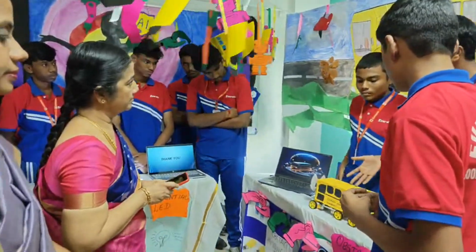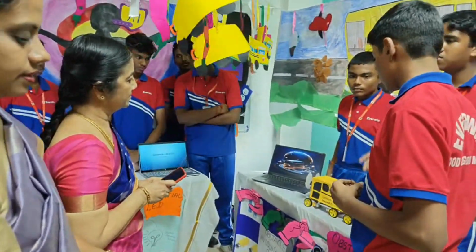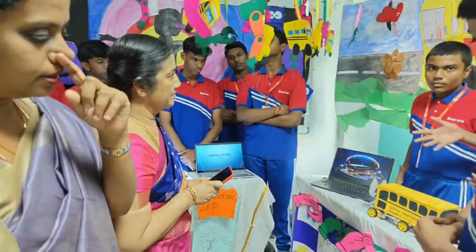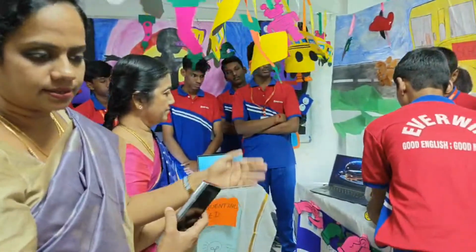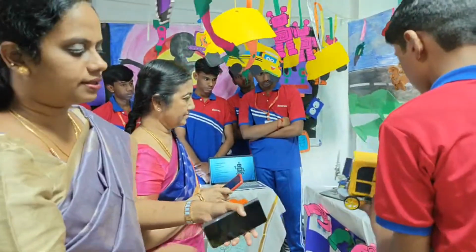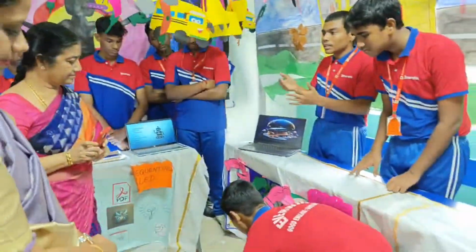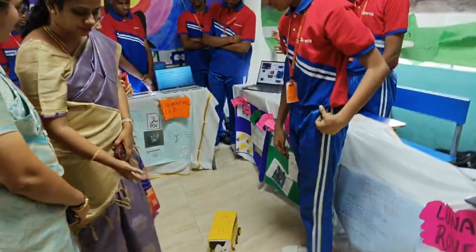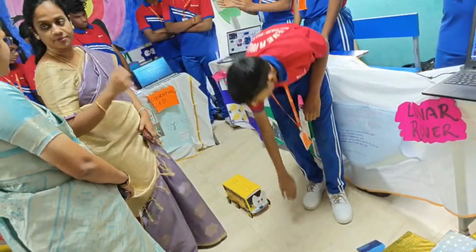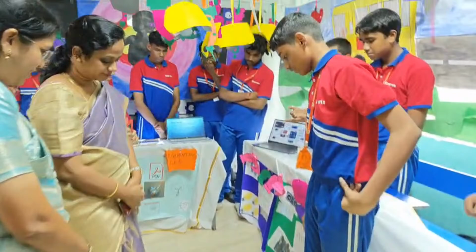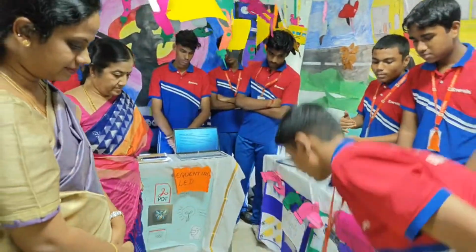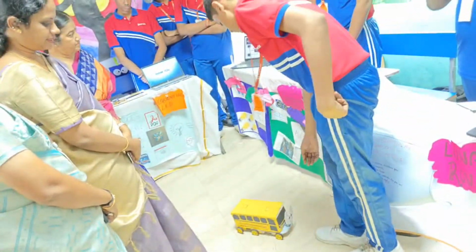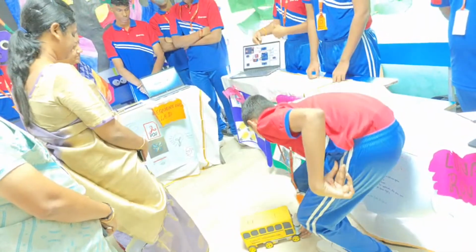The main electronic components present in this vehicle are Arduino, ultrasonic sensor, and gear motors. The working mechanism is that the ultrasonic sensor detects the obstacle and tells the Arduino the distance of the object, and it makes the robot motor navigate in the proximity of the object. And it flashes the signal to the motor driver for the DC motor, providing positions. The gear motor moves either clockwise or anti-clockwise.